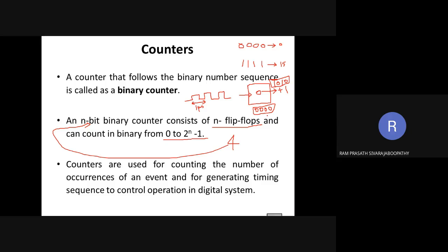See, a timer is nothing special; it just counts the clock pulses we give. That's all. Clear? Is it clear or not? Based on the timing of your clock signal, it is going to generate some timing for each count. For example, if the count reaches 20, what will it be? 20 microseconds, correct? See, our digital watch or clock, everything works on this principle only. Clear? Digital clocks all work based on this principle.